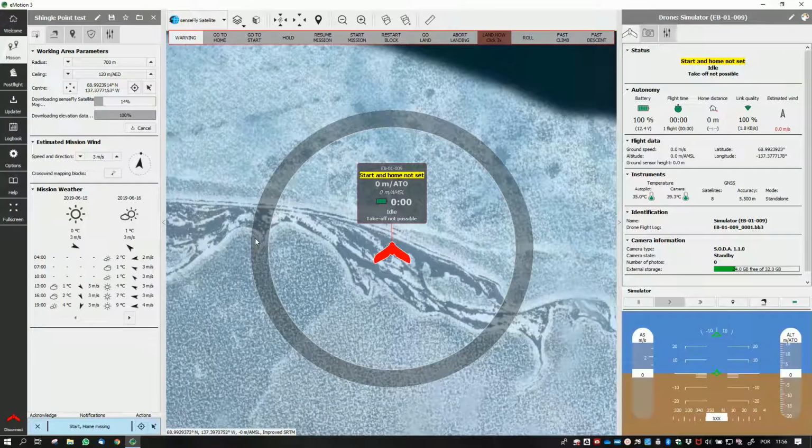And then before starting to do the flight plan, I would like to emphasize on a few things which are important. So in this area, you see warning messages, which you may be able to acknowledge by clicking. So if you have a yellow warning, you can acknowledge it and it will just flash again white. This yellow warning is not really a very important, significant warning, but you have to be sure what it says. And here you have several virtual keys which you will hit depending on what you need to do.